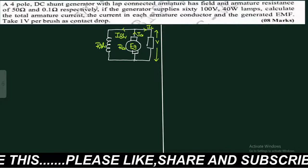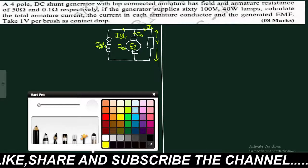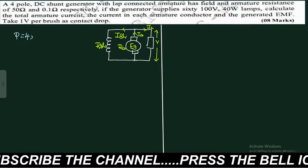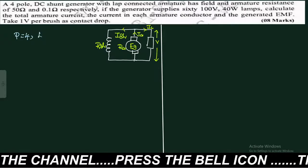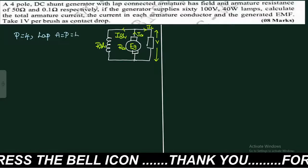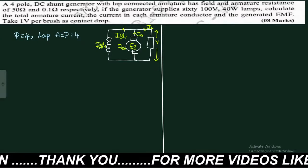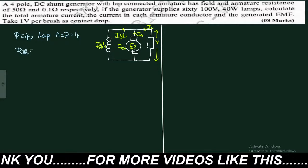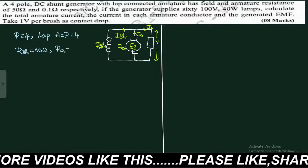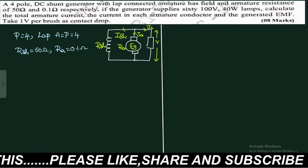Now let us write the given information. A 4-pole, that means the number of poles is 4 here. DC shunt generator with lap connection. Lap connected means you have to remember A equals P, that is equal to 4. Field resistance RSH is given as 50 ohms. Next, armature resistance is given as 0.1 ohm.